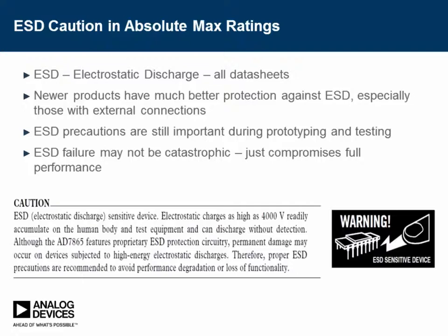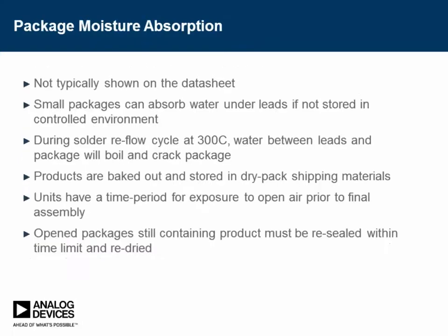So use ground straps and whatnot. Now again, ESD failure is not necessarily catastrophic. The product could still work for a while. It might not work the same. So it's important to use all the cautions during use of the part.